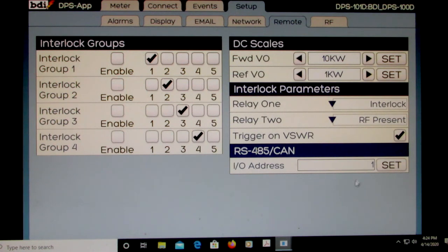And then, of course, we have our SWP206 Digimonitor antenna monitor system, which can accept up to 8 meter inputs, so we have 8 different addresses, and you would set each individual meter up here to do that. We're going to leave it set to defaulted to 1 because we only have the 1 meter that we're concerning ourselves with.